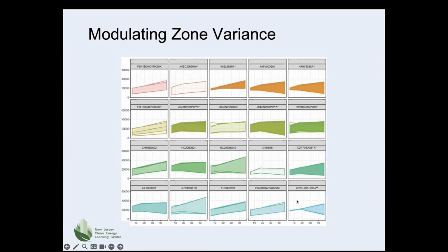And then some products, when the outside air temperature goes lower, they tend to decline in their capacity as well. And you can see here on this, in the second row, the first box rather in the second row, how the capacity is quite a bit lower as the outside air temperature declines compared to others, where the capacity is still somewhat high at the lower temperatures.